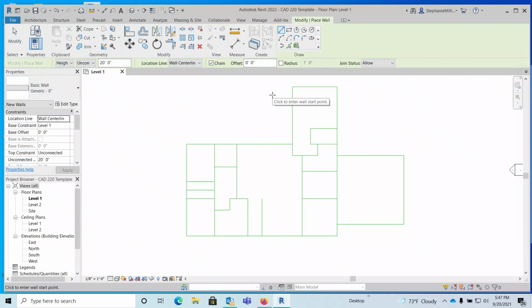If you do this, what you need to pay attention to before you create your walls is, one, what type of wall, and two, where are you measuring from? And that's called the location line here at the top. Since I just said I'm doing exterior, then I'm going to say I'm on the finished face exterior when I pick my points. That way I can tell which side my wall is going to be on. And since I was very adamant to do 32 feet, I do not want to be any wider than 32 feet. So by doing this, I just want to do exterior.